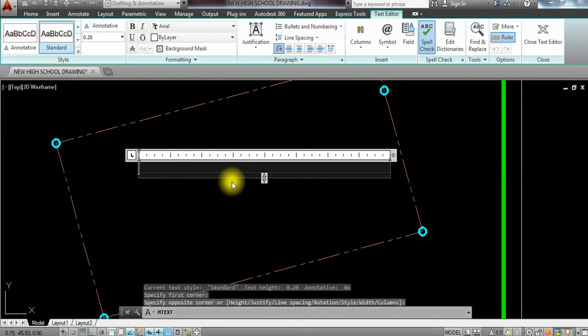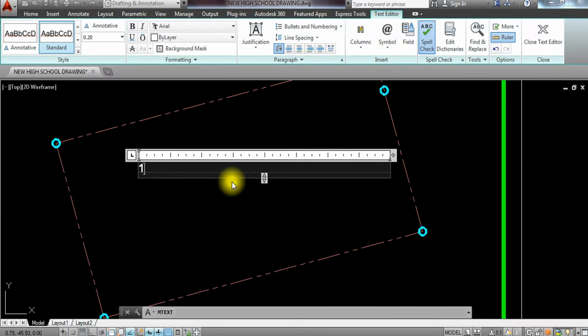So for example, here we will put first the position of each bearing point. 1 to 2, distance is south 16 degrees. On how to type the degree symbol, just press %%D, and the degree sign will appear, with 29 minutes east with a distance of 6.47 meters.